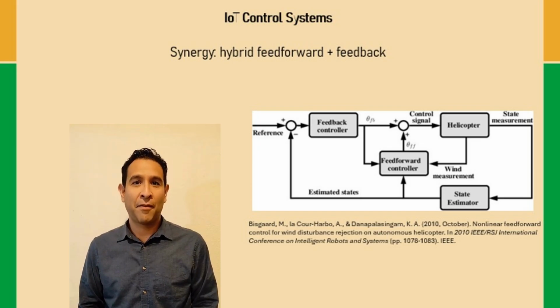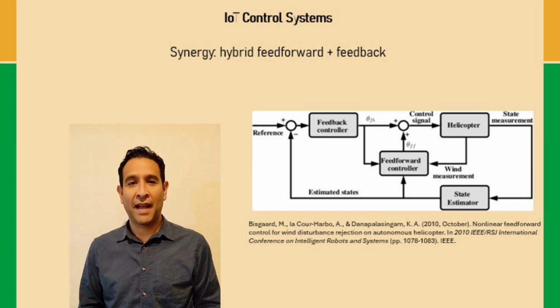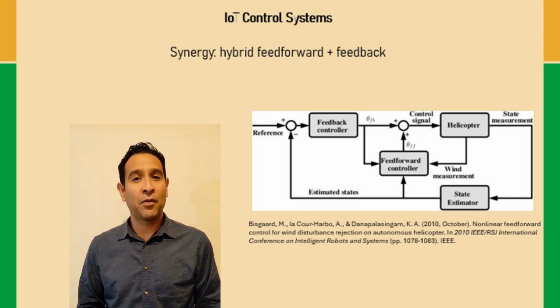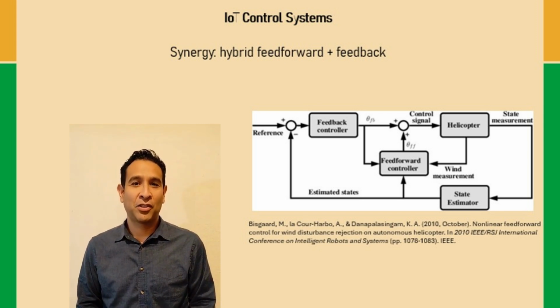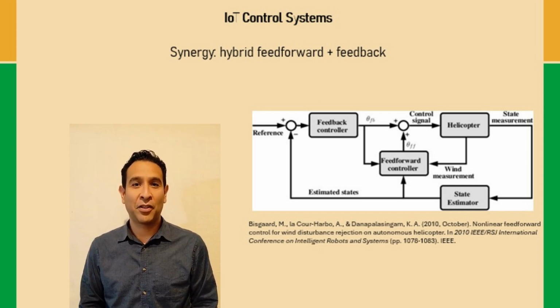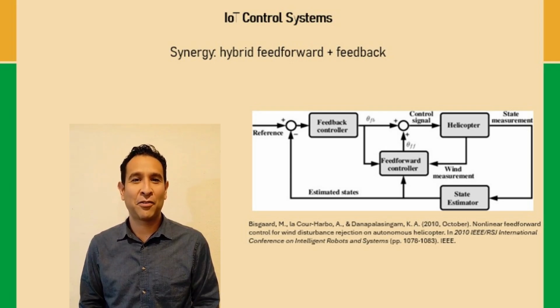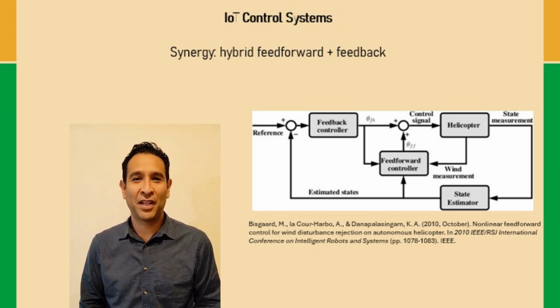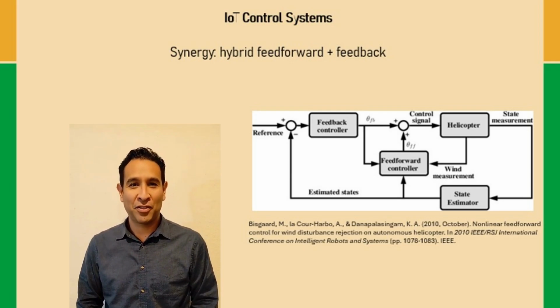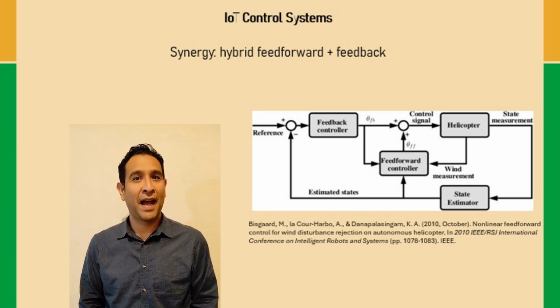To wrap up, feedback corrects, feed-forward anticipates. Together they deliver responsive and stable IoT control. As you design, start by defining the set point and sensing chain, tune a reliable feedback baseline, then layer in feed-forward where you can measure and predict disturbances. Keep models simple, filter wisely, and validate with step tests and safety limits.